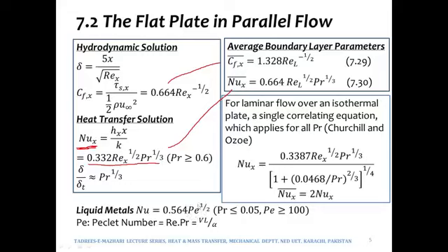So over here another dimensionless number, Peclet number, is defined, which is a simple product of Reynolds and Prandtl. So it is in fact written as 0.564 Reynolds half Prandtl half, and the product of Reynolds and Prandtl has been written as Peclet number. But this can only be used if we have extremely low Prandtl number, which corresponds to liquid metals only.